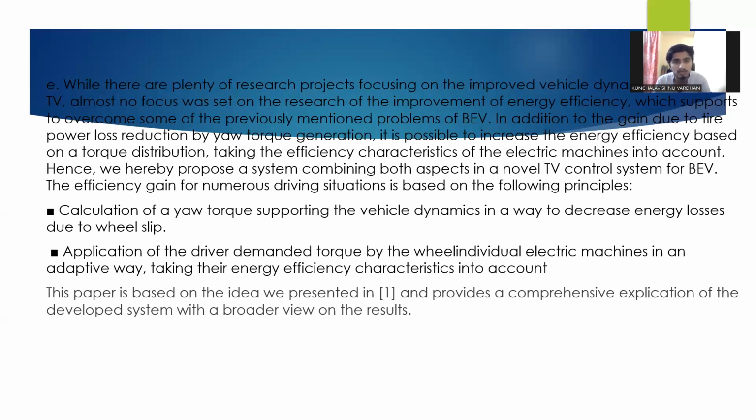Hence, we hereby propose a system combining those aspects in a novel TV control system for BEVs. The efficiency gain for numerous driving situations is based on the following principle. Calculation of a yaw torque supporting the vehicle dynamics in a way that decreases energy losses due to wheel slip.